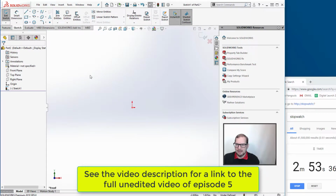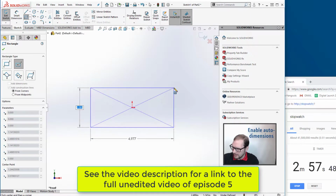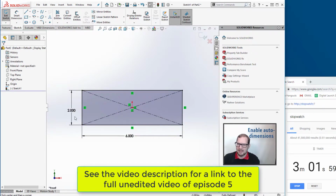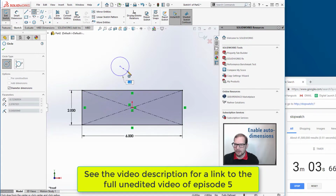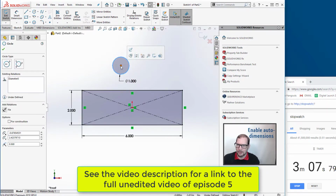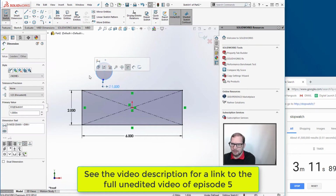And what that means is now when I press the S key and I choose rectangle, I can single click here, move my mouse, let go of the mouse, 2, enter, 6, enter. And I've got a nice fully defined sketch with dimensions already on there. If I make a circle here, 1, enter, I've got a nice, defined diameter for that circle as soon as I'm sketching. Huge time saver, really awesome bit of functionality in SolidWorks.